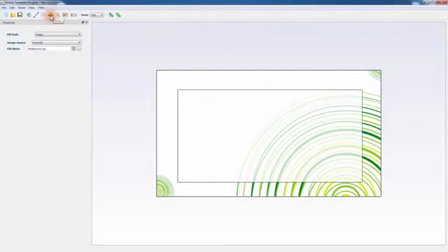To activate the created scene states, create buttons and link them to the scene states. To do so, create a rectangle, and from the panel to the left, adjust its appearance as you see fit. Since there are 6 scene states created earlier, we would need to create 5 more buttons, or simply duplicate the existing rectangle by pressing Ctrl and C and then Ctrl and V. Or you can right-click the rectangle and select Copy, then right-click again on the template and select Paste.